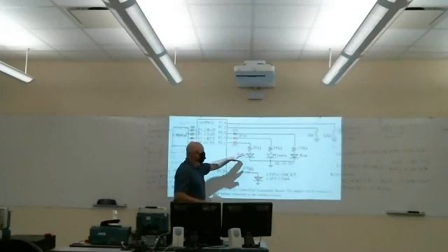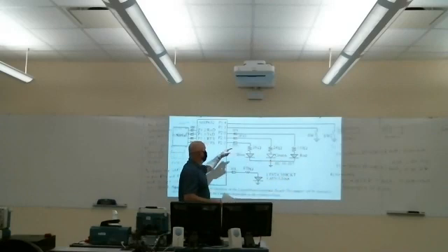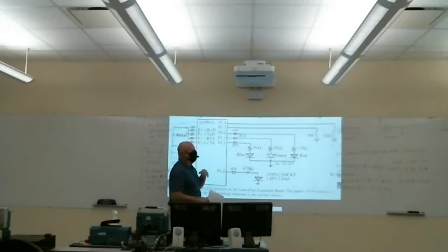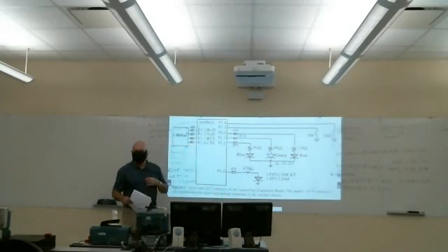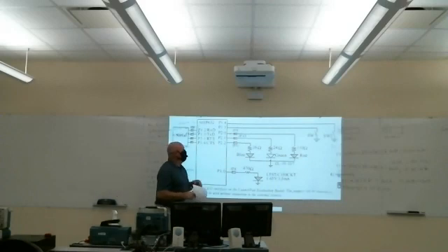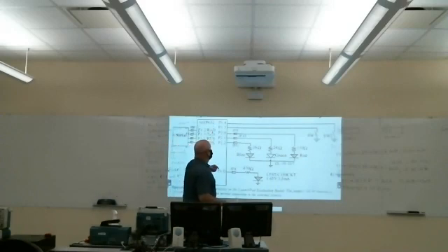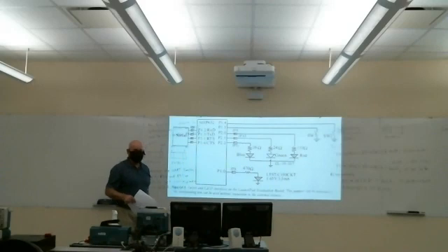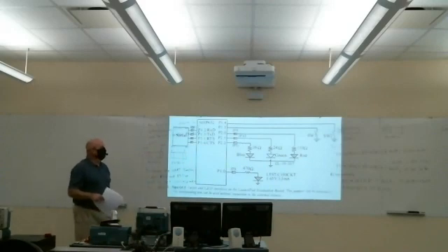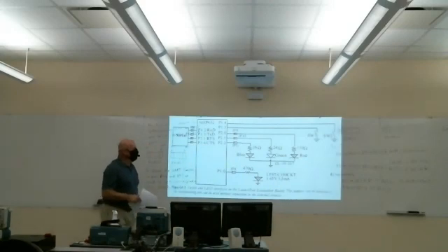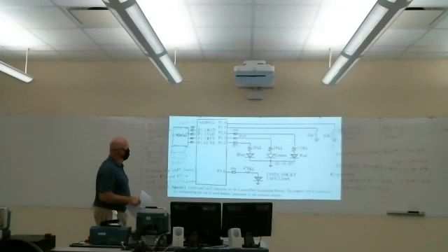And if you want to turn on the blue LED, that's pin 2 on port 2. We'd write a 1 there. The switches are connected to 2 pins in port 1. Pins 1 and 4 in port 1. So we can directly read those switches on those two ports.